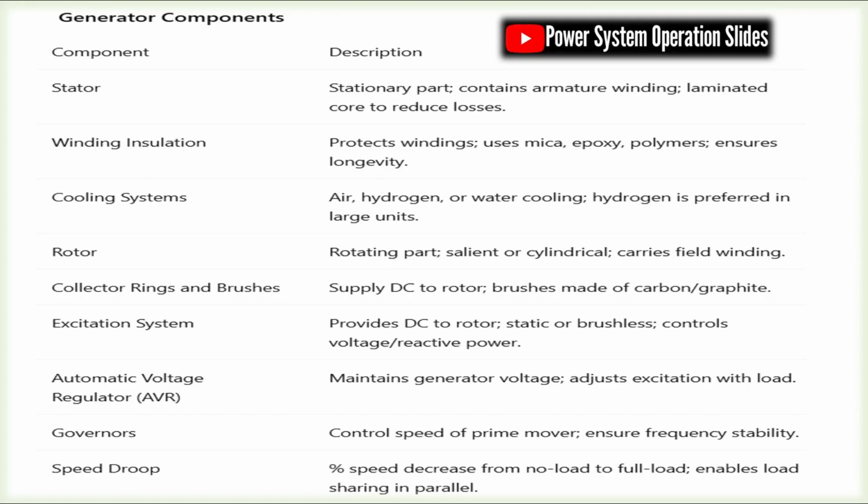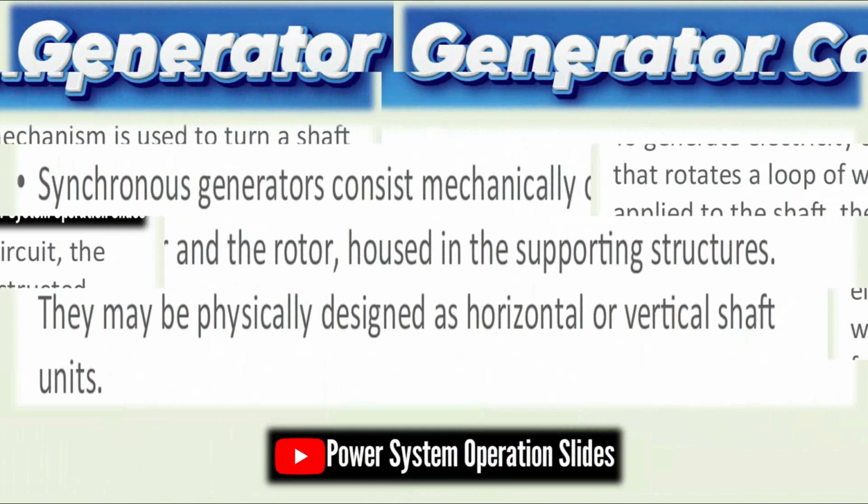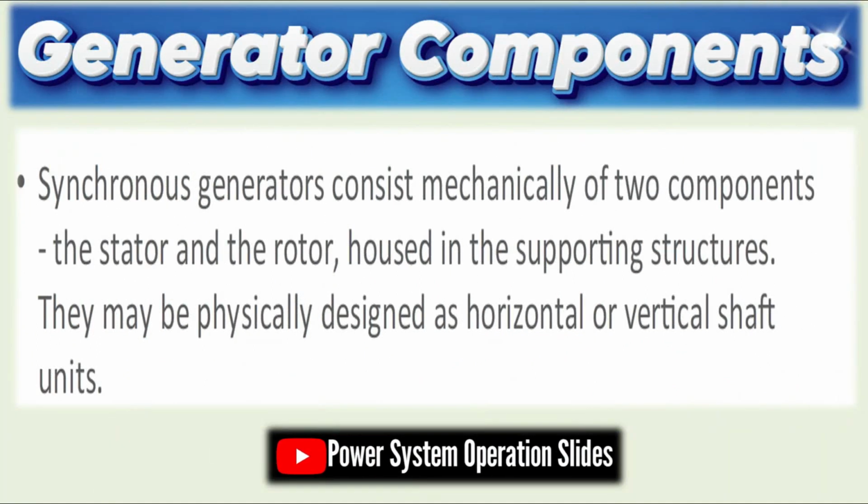In pressurized water reactors (PWRs), the primary loop heats water under pressure, preventing boiling. This transfers heat to a secondary loop via a heat exchanger steam generator. In boiling water reactors (BWRs), water boils directly in the reactor core to produce steam. Advanced reactors include fast breeder reactors, which produce more fissile material than they consume, and small modular reactors (SMRs), which offer scalable, safer solutions.